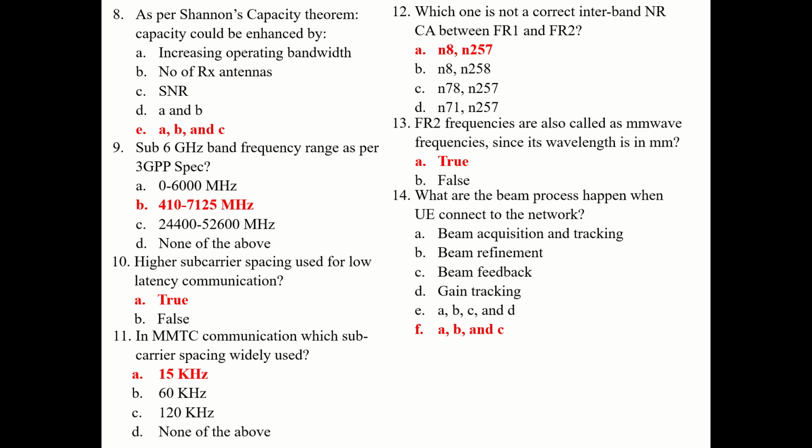Then it will update the channel state information through the channel state reference signal, so it can capture the particular beam acquisition and then track. When the UE is in movement mode, one more thing is that the SSB block has a 20 millisecond periodicity. Every 20 milliseconds it will always sweep the beams to check whether any UE is there or not.